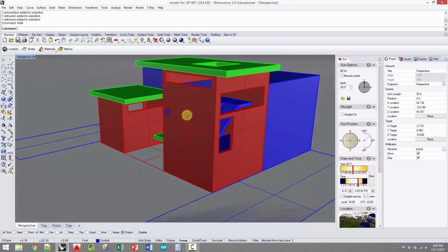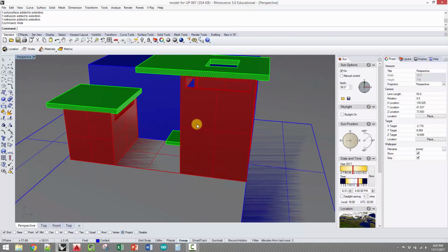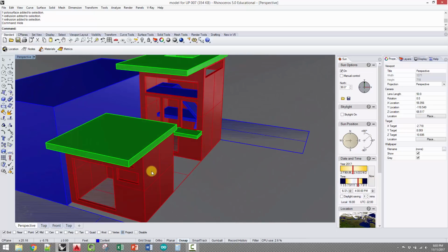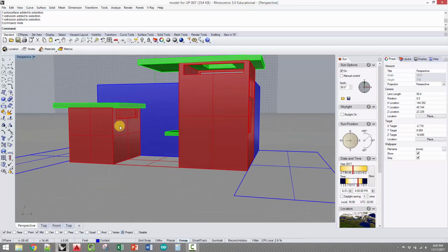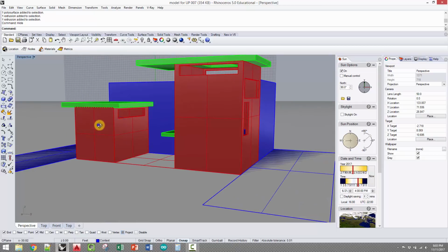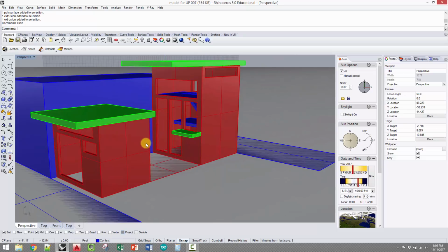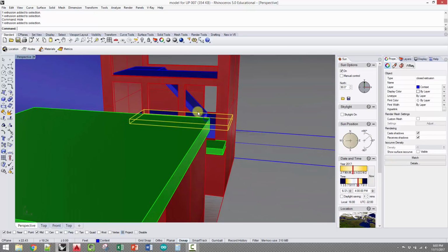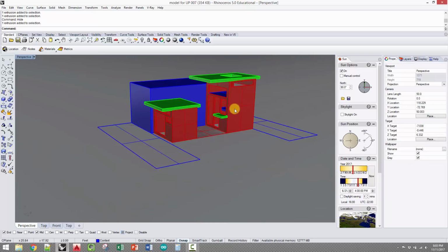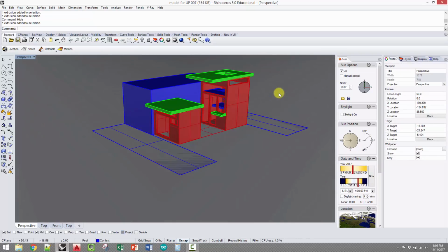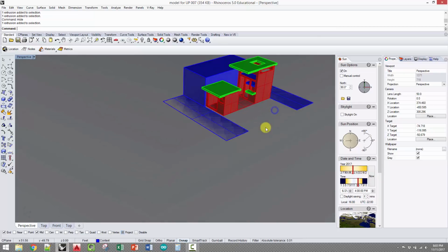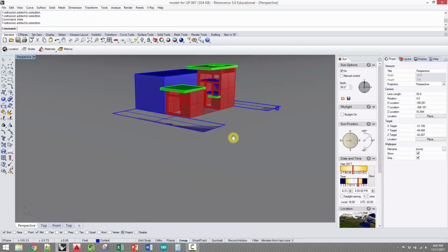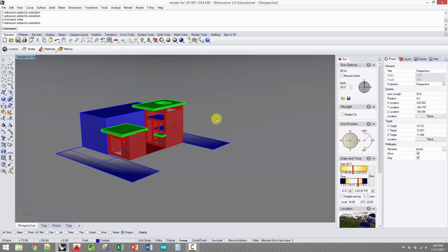All we're really looking at here is simulating the effects of the daylight within the space at different times of day. And this is going to use a lot of things that we've already done in VRay. But this is the kind of quality of model that you need. So you just need to make sure you got your overhangs, make sure you got any kind of large openings that are going to be holding glass. Doorways are not really that necessary. You do need interior planes because that's also going to affect the way that light works in the space. All right. And in this case, I did do an infinite VRay plane, just to make sure that there's a place for light to bounce.